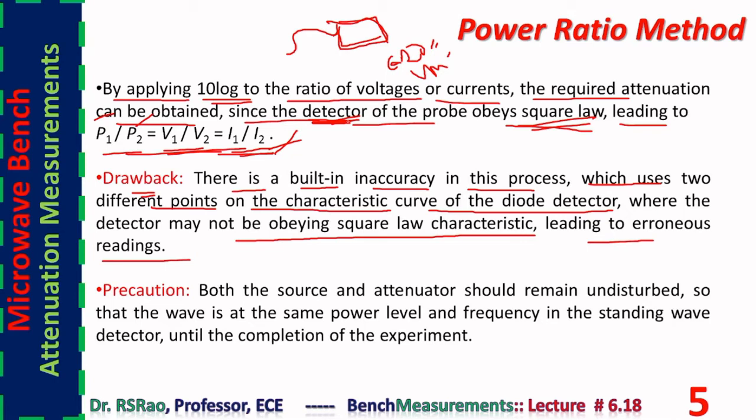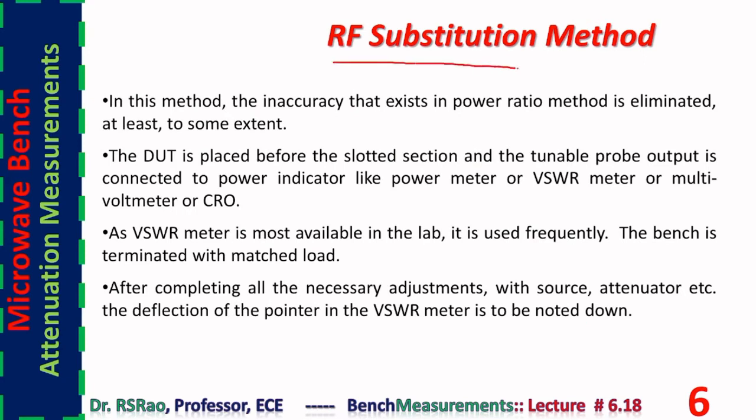Precaution. Both the source and attenuator should remain undisturbed so that the wave is at the same power level and frequency in the standing wave detector until the completion of the experiment. Another method, RF substitution method.